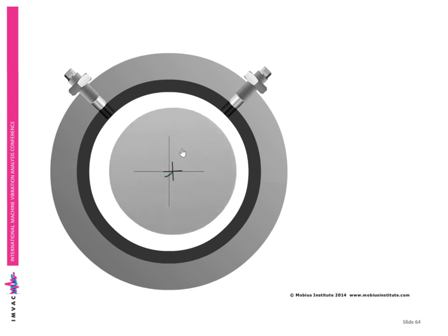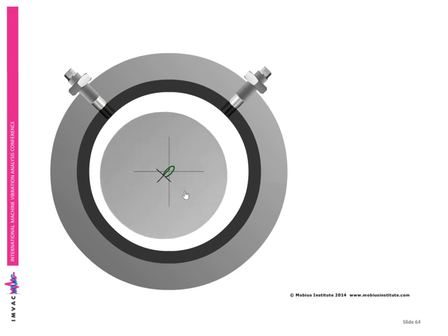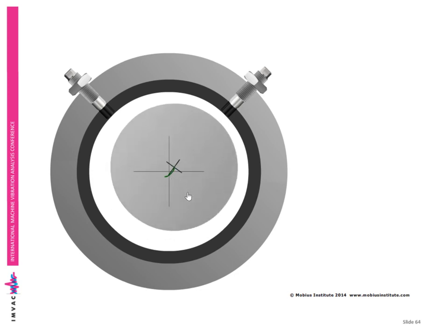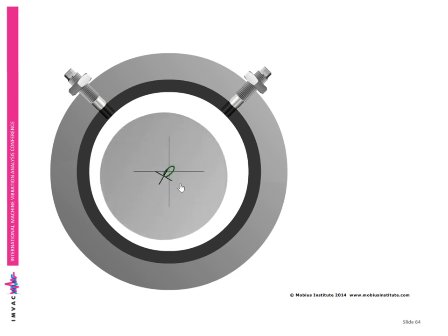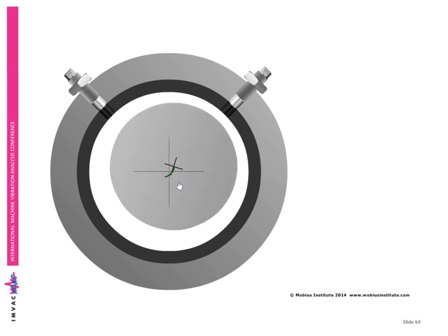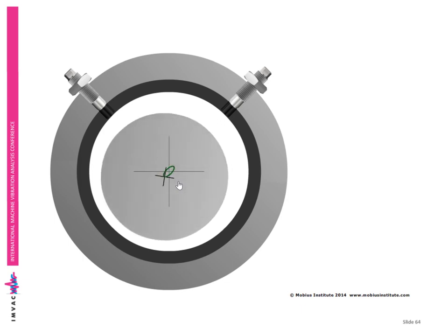Now it just so happens that if I knew that was actually happening, I might be a little concerned, because it shouldn't be there. It should be down in this quadrant here for a shaft rotating in a counterclockwise motion like that. The bearing has a certain amount of clearance.